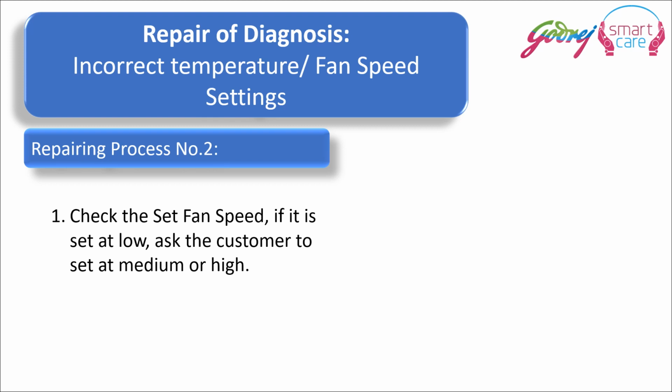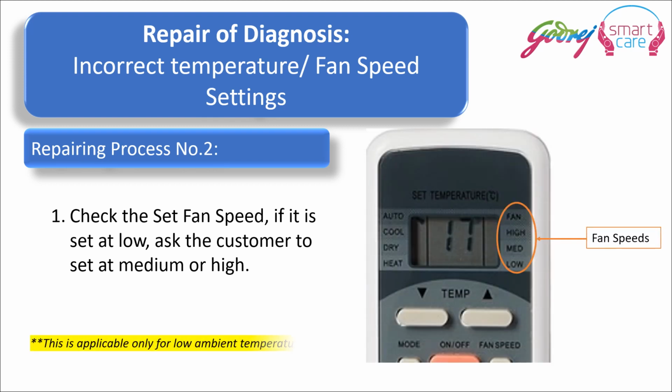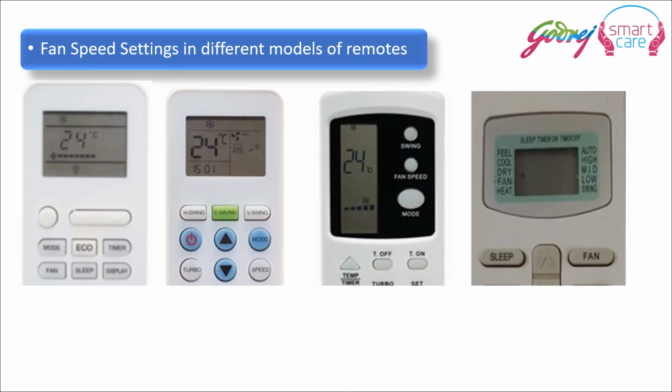Check the set fan speed. If it is set as low, ask the customer to set it as medium or high. Fan speed setting in different models of remotes is shown.